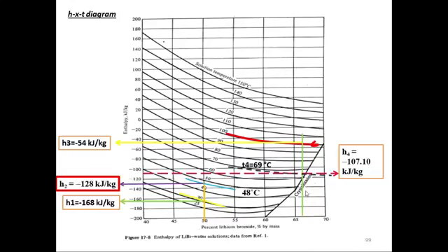So here is that line. So we are getting the concentration at point 4 was 66.4% right here, and we know the enthalpy value is 107.10, as we have calculated by energy balance. So the point is where your enthalpy 107.10 is. The dashed line here, the brown dashed line, is the enthalpy line that we have drawn, and here it is the concentration line. The green line is the concentration line. The solution line must pass through this line.